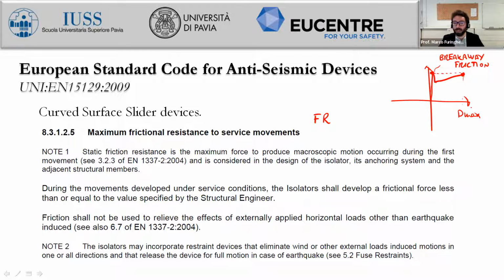The breakaway friction can be much reduced if we consider lubricated sliding materials, obviously, but in the same way you are also reducing the friction generally. So you have to check if your application needs actually a low friction, rather than a given specific value of a friction coefficient. So you need just that value of friction coefficient with no breakaway.